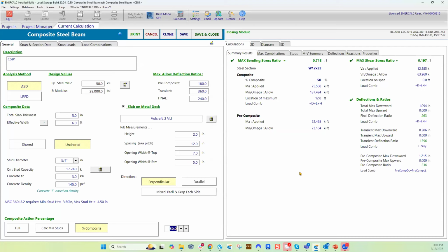I just want to make sure that at least everyone is aware of the deflection calculations. So if we're doing pre-composite state and you're applying load on the bare beam, then you're using the standard moment of inertia of that section. But if the load that you're applying is post-composite, then that portion of the load gets checked against the lower bound moment of inertia, which is of course a lot higher, and it's going to help you a lot with deflection since it considers the composite action. So your deflection calculations that you're getting are pretty accurate, as sharpening the pencil as you can get.